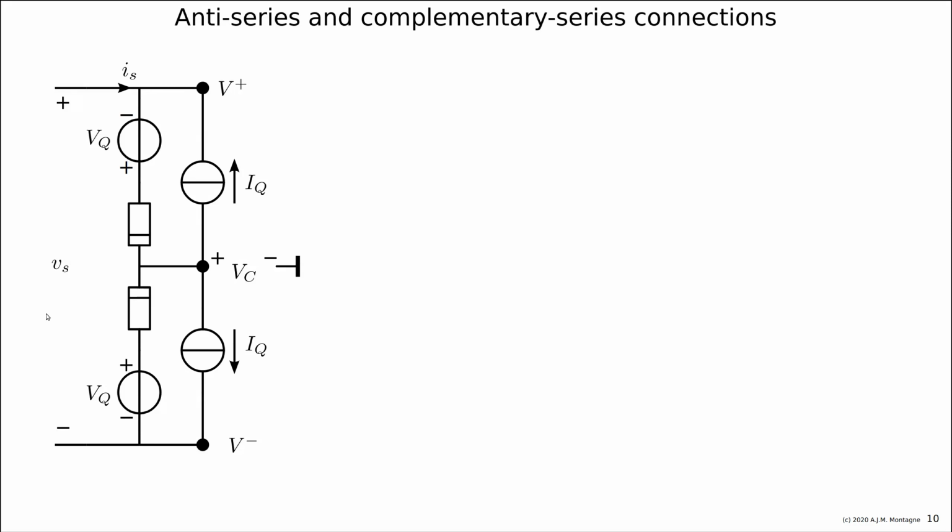So the series connection, the series voltage plus minus VQ, is exactly zero when we are in the quiescent operating point when we apply no signal. And there is no current as well. So you can terminate this two terminal element with any other elements. You can place it in series, in parallel, and there will be no current through it or voltage.